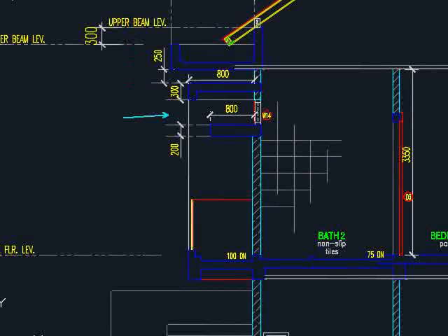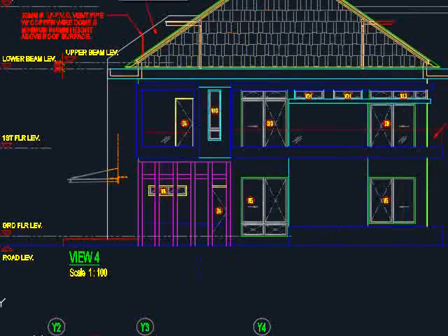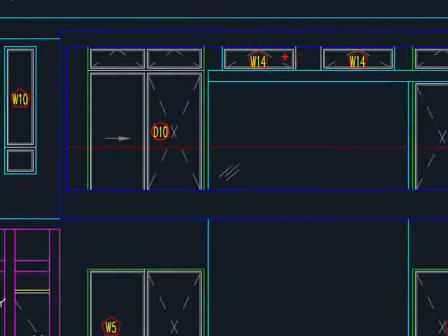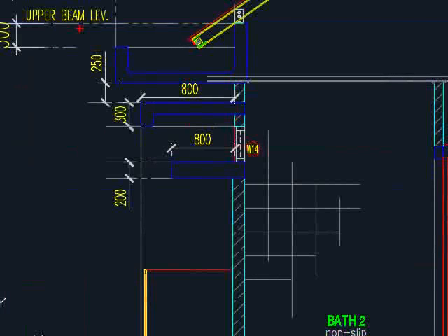And then you will need to check from the side of the building, which is the view 4 of the building. We are talking about this gutter, this architecture thing. The windows are here, and there is another extension here. You will need to find a mechanism to support this part. Probably you might need reinforcement bar along here in order to hold this piece of concrete element. These are something that you have to take into consideration.